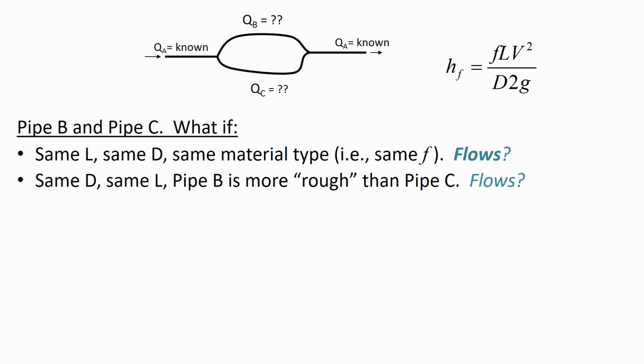Whoa, he's got it. He's onto something. Okay, go ahead and say it. The total head loss from, I guess you could say, the junctions. Okay, the total head loss through the junctions. You're almost there. The total head loss what? There has to be a conclusion to that statement. Through pipes, okay, compared to the other one, because the epsilon values would be different. What did you just say? The epsilon values would be different if one pipe was less rough.